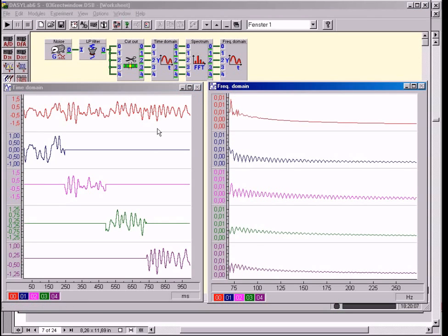The lower 4 signal segments contain considerably more, or rather stronger frequency ranges in this area than the overall signal at the top. Thus, cutting out partial segments produces frequencies which were not contained in the original signal. In addition, the link between the individual segments of the signal, which have been separated arbitrarily, is lost. This may mean that information has been cut up. Information consists of certain agreed patterns, see Chapter 1, and therefore lasts a certain time. In order to capture this information in its entirety, the signal segments would have to overlap as a precaution.